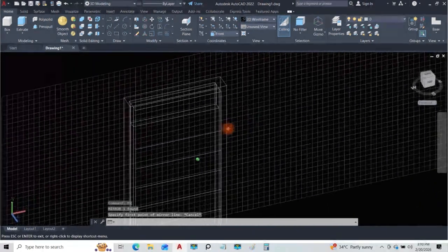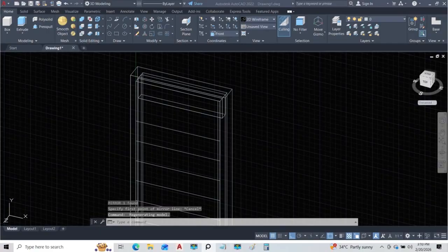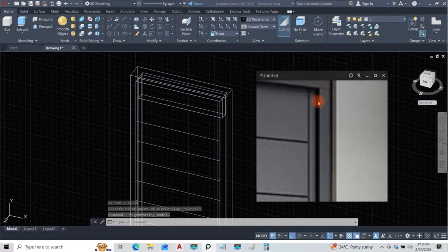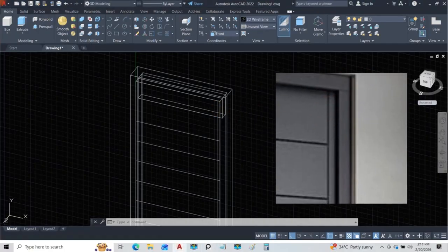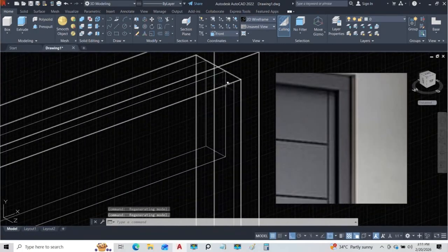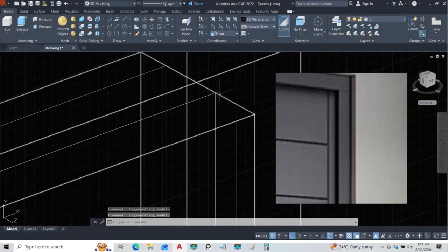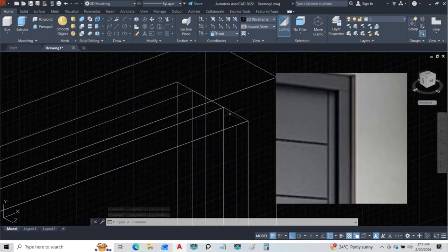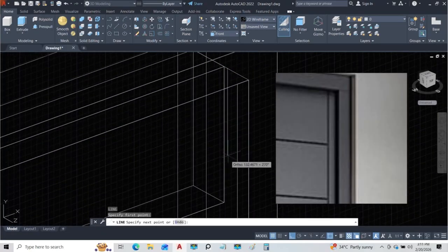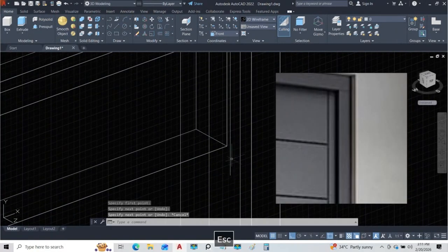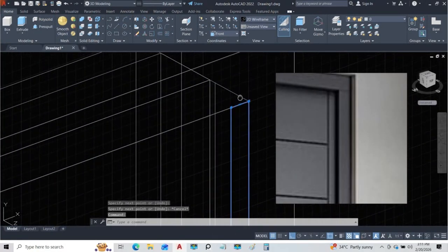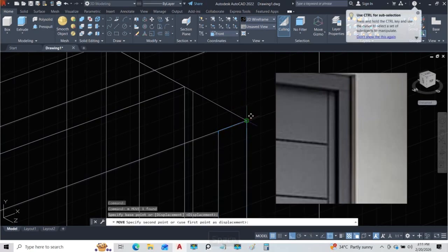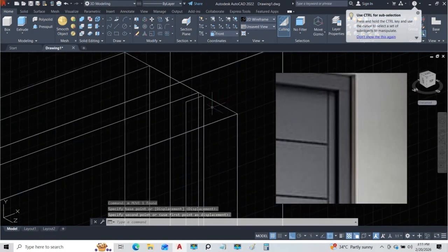And then the other thing I'm also going to do is, if you look at this, it's also not at that surface, and also not at this. It's just a little bit projected forward than this depth. So what I can do is here I can create another line down so that I can move that rectangle there. So let's just create a line here. All of these things I'm doing, we are going to remove them. They are just for construction purposes. So I'll select this, M for move, click here, all the way here.